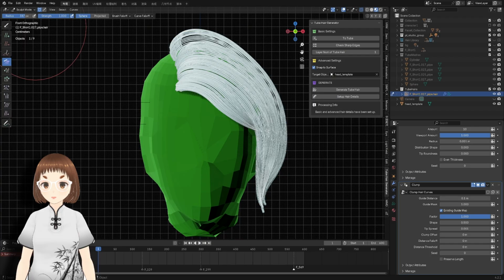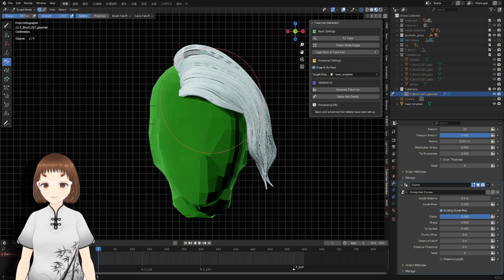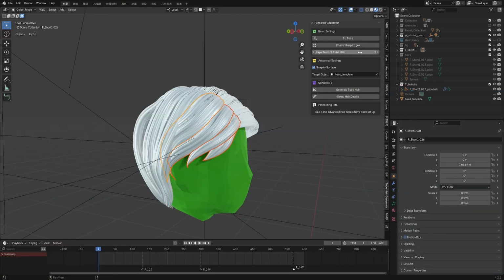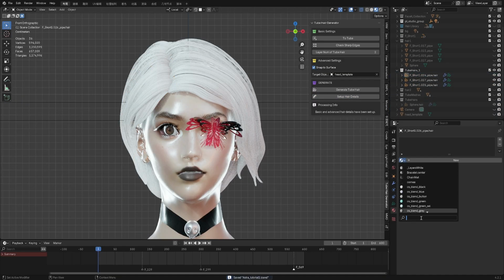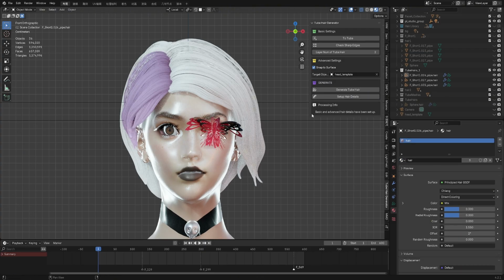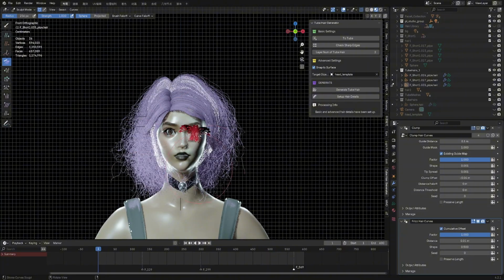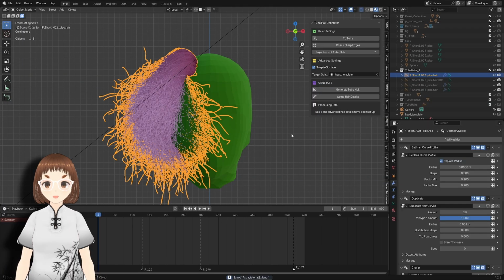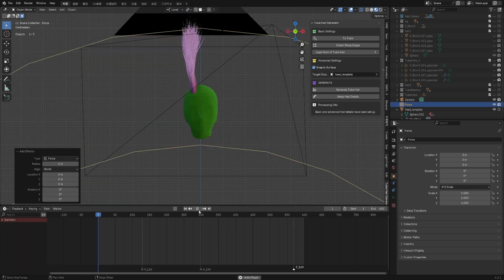Then switch to Sculpt Mode. Use grooming tools like comb, puff, twist, and smooth to continue artistic styling. From this point on, the technical setup is done. Now it's pure creative work. For further production, you can also assign hair materials and refine geometry nodes effects. Convert to a particle hair system, or integrate into rigging and animation workflows.